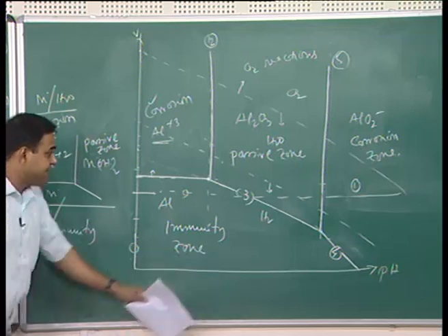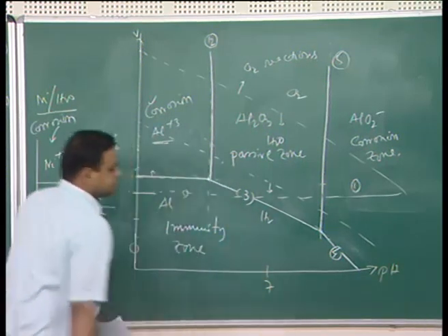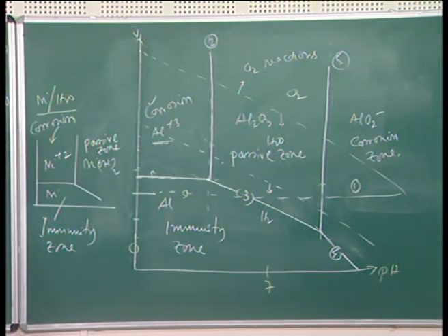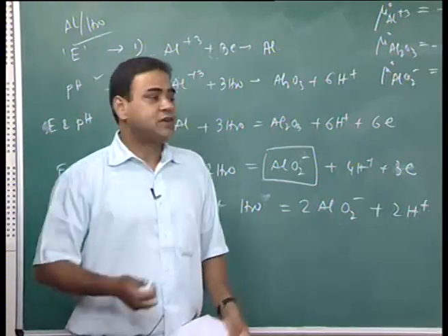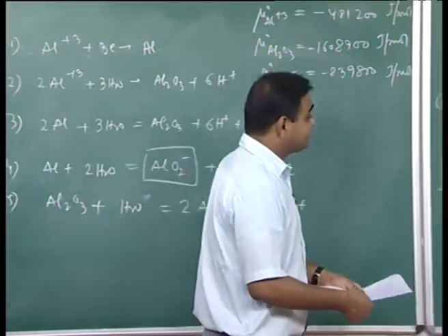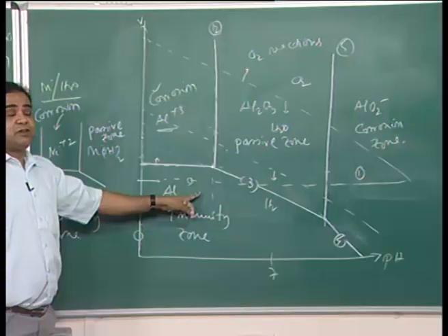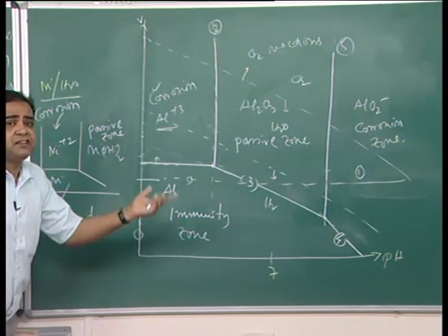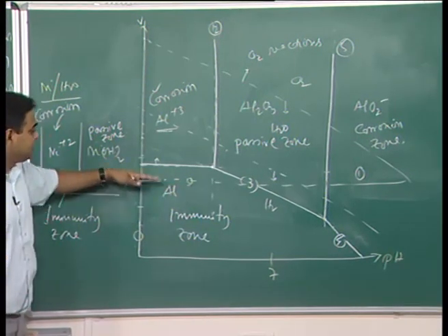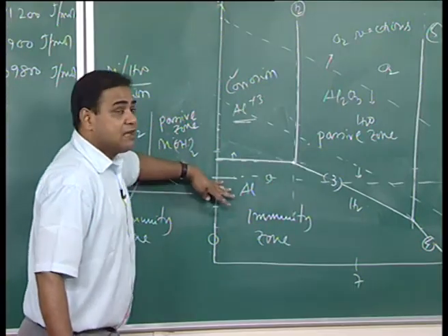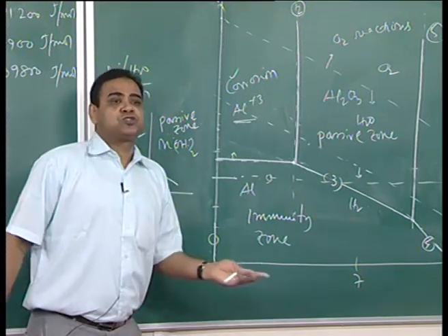If this is pH 7, the neutral solution, we have the common understanding that if the acidity increases we have more corrosion. But that does not happen in this case, because even in a very highly acidic medium, if your potential is below a certain level, you can have no corrosion.